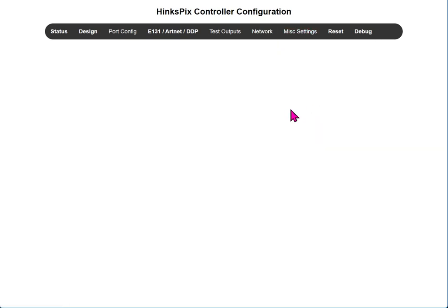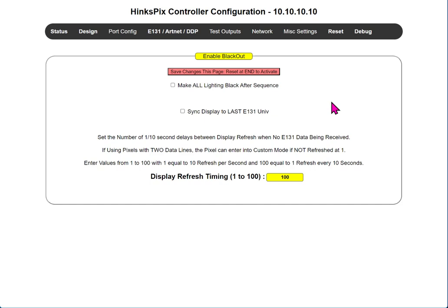We have blackout show. The inherent nature of DMX is that any particular output, once received, does not change. In other words, if you output and tell a pixel to turn blue, it will remain blue until it is told to change to another color. It is not uncommon for people to have sequence data being sent to the controller live, and when they're done, they wish for the lights to actually be off, which is not typical DMX configuration or spec.